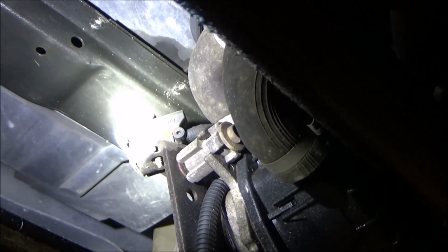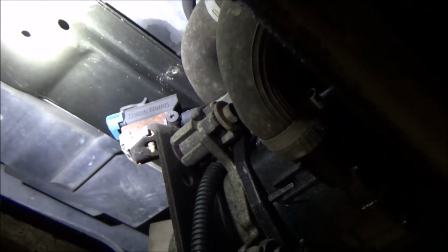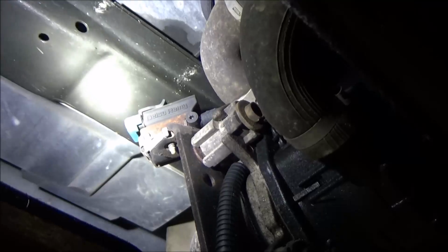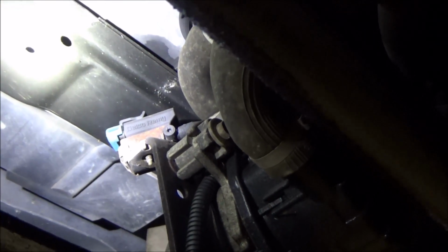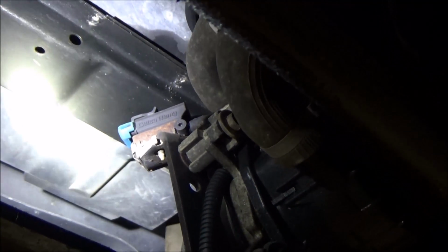We know the pump does not run, but I'm going to energize the relay, and we're going to look and feel on the solenoid and verify that it is in fact working. So just to keep it low tech, not even going to do any voltage measurements as far as this test is concerned.